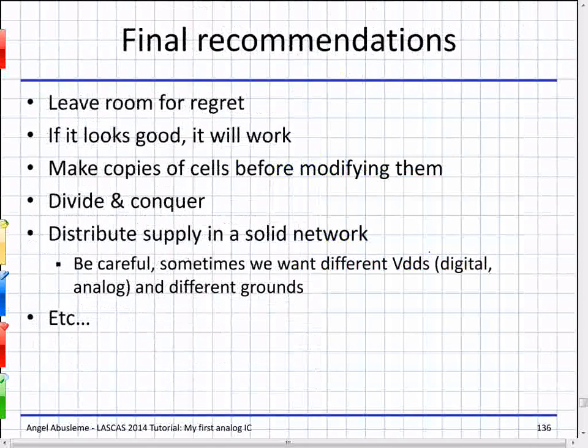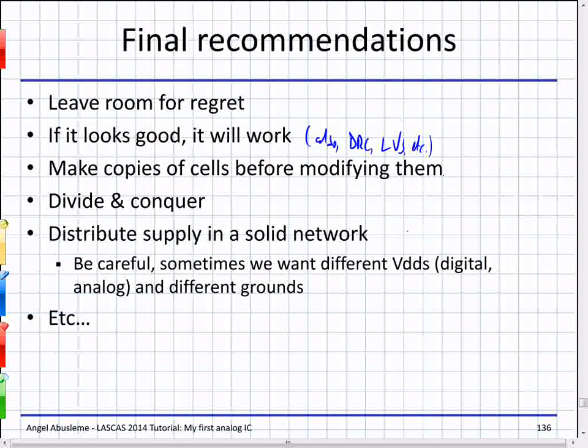Okay, more recommendations. Leave room for regret. Always leave some extra room because you might use that later. If it looks good, it will work. Well, that's also, remember, DRC, LVS, etc. Make copies of cells before modifying them, and divide and conquer. Start with small things and then put them together.